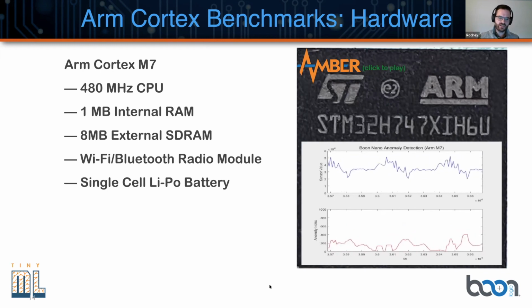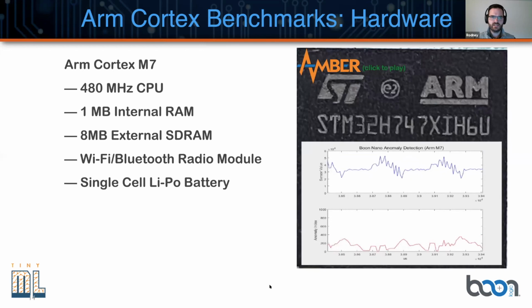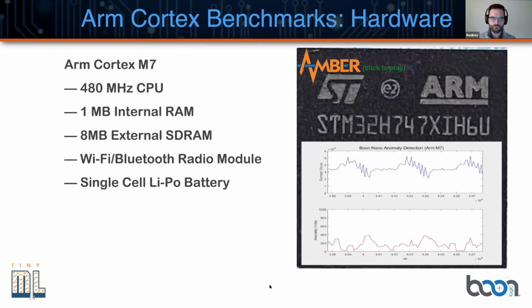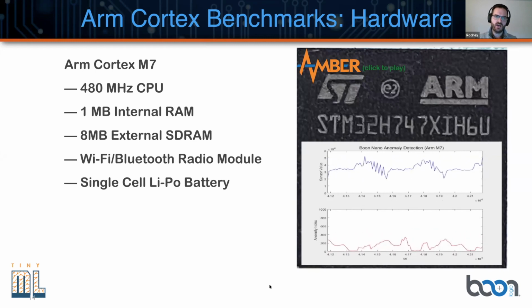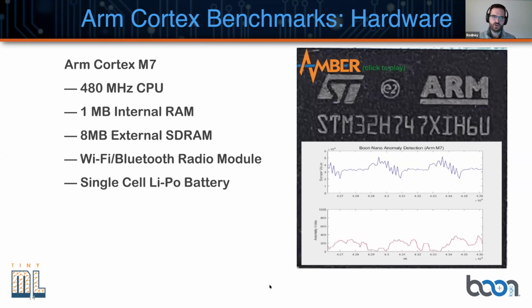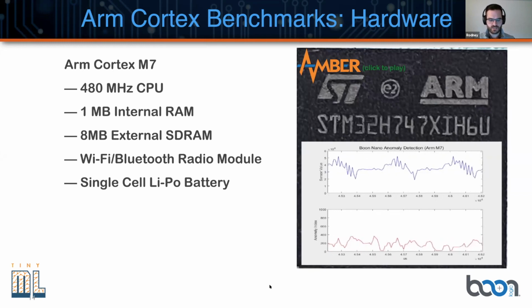The signal that we're looking at here is the same current signal from those Allen Bradley motors that Brian discussed earlier. Here though, we're reading in that data directly into the ST microchip via the analog ADC. We can also support I2C, SPI, those kinds of digital formats. So the first step in the pipeline is to just acquire the next sample. We add that into our feature vector, and then we start clustering and computing anomaly indexes.